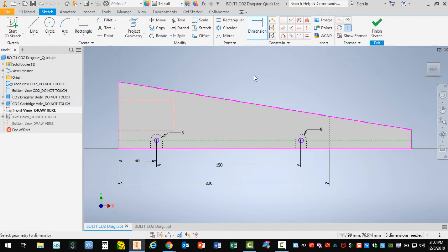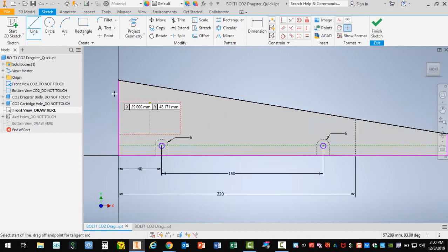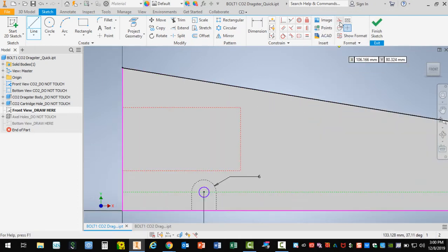I'm going to draw a car very quickly here just to demonstrate three very common tools. Let me start with the line tool. So I'm going to click on line. Shortcut to that is the L key. I'm just going to zoom in a little bit here. Keep in mind construction line is turned off. I do not want that on. My car starts here on the back.